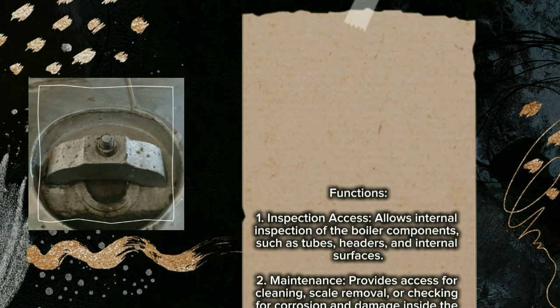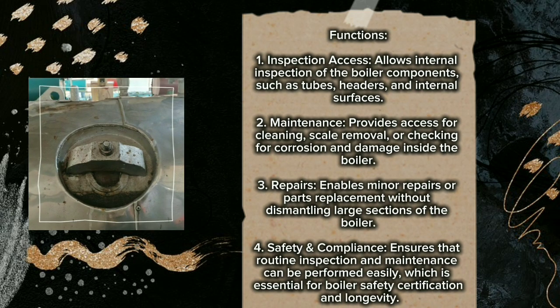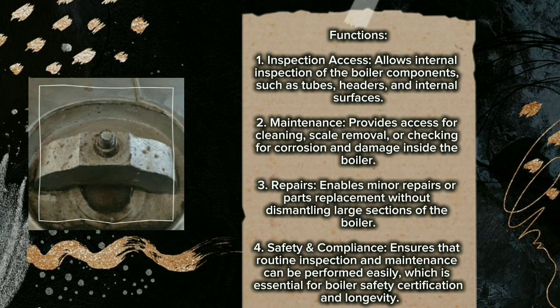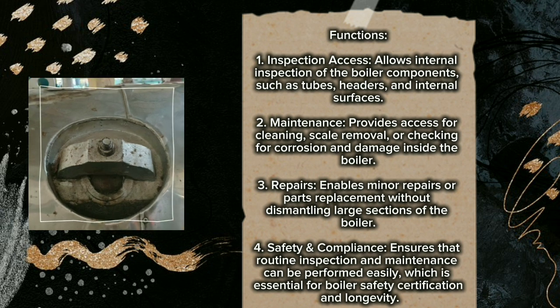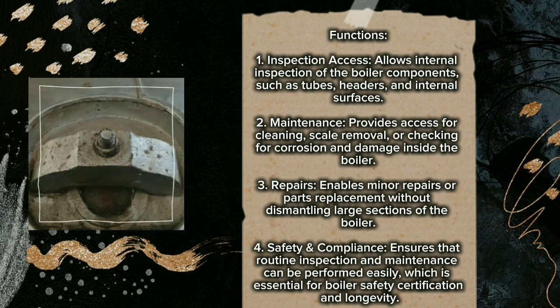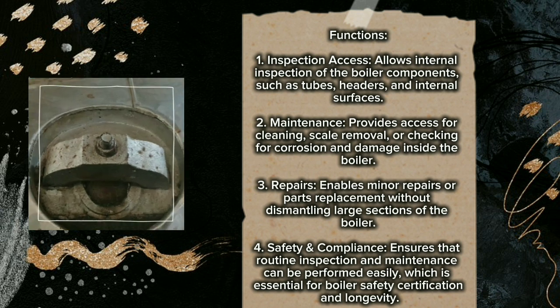For its function, number 1, inspection access. Allows internal inspection of the boiler components such as tubes, headers, and internal surfaces. Number 2, maintenance. Provides access for cleaning, scale removal or checking for corrosion and damage inside the boiler.